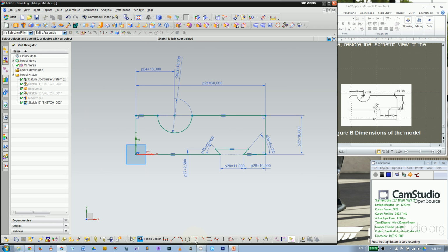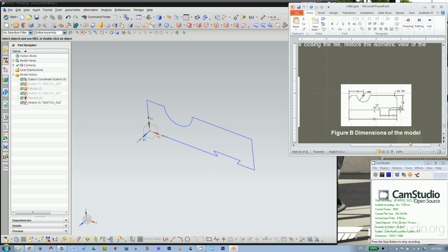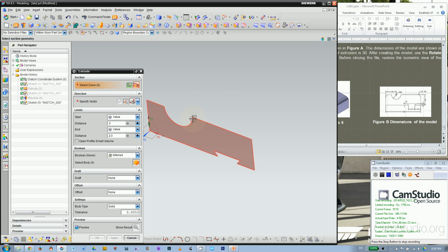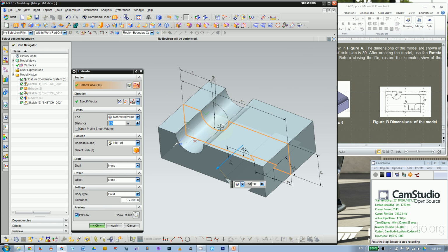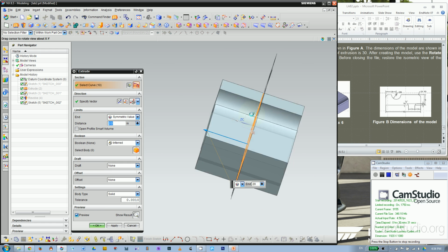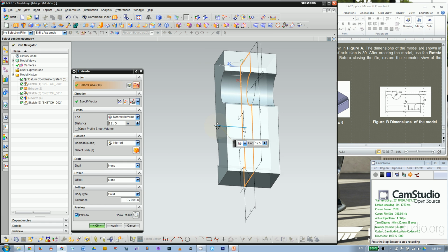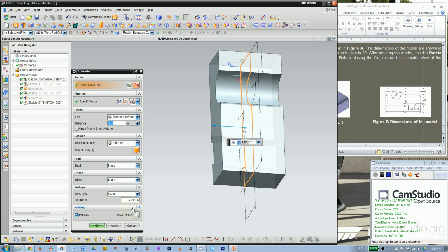Then we can drop in those two fillets, and you know what? I'm gonna use edge blend instead of fillet. So I'm good in this sketch already. Okay, and I'll just extrude this sketch, probably symmetrically, so you know there's a symmetry on this part. It's symmetrical in the middle, so probably 15. Okay.